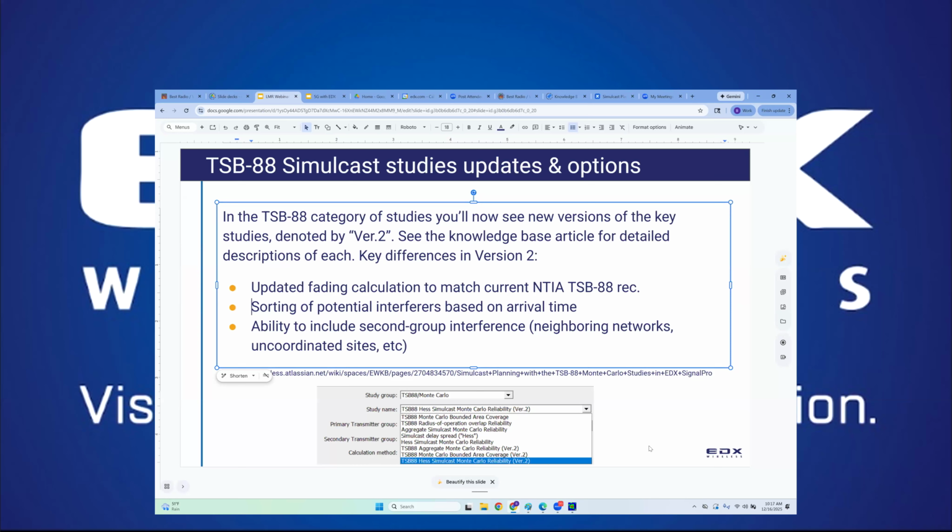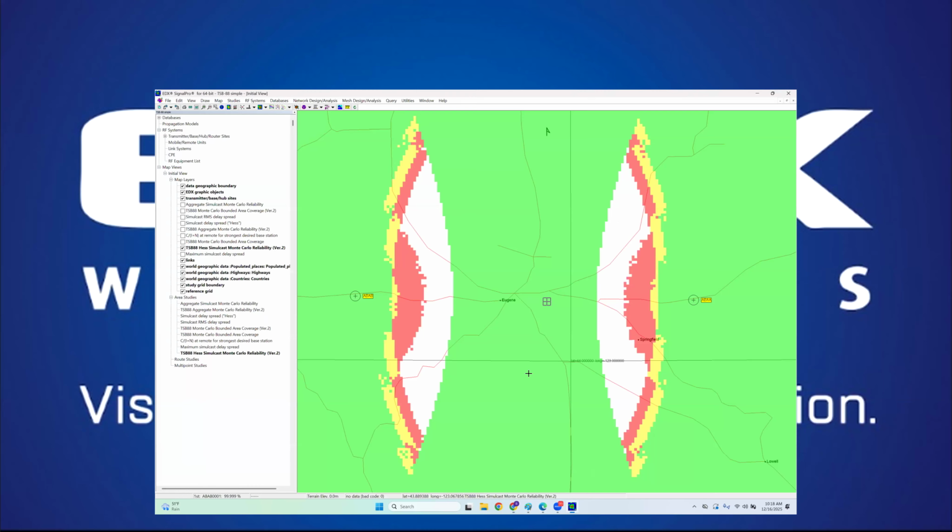Whereas as soon as the distance between the two sites hits the right distance for that delay value to be outside the allowable time delay window, then that signal power will count as interference and it will effectively degrade the signal to noise ratio that we're using to try and reach the channel performance criteria.